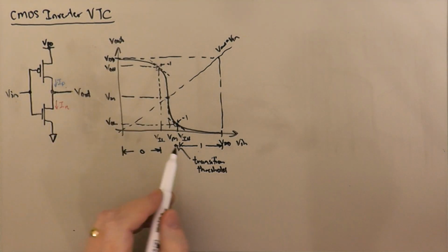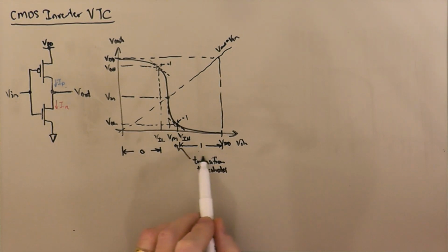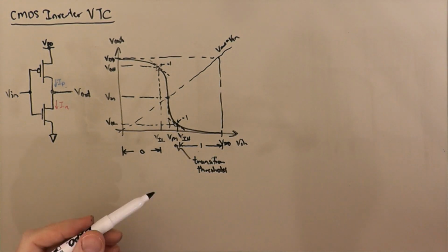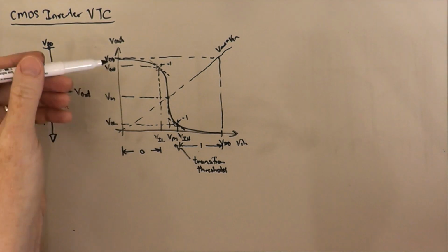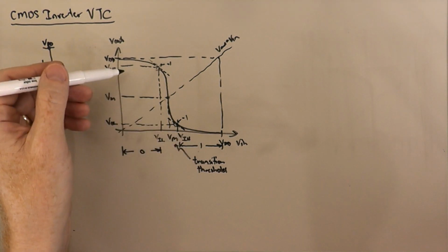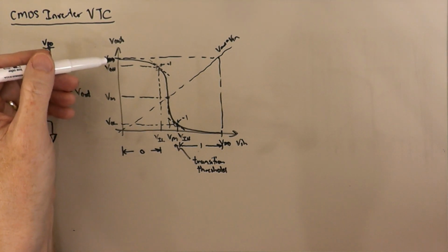Okay, so these ranges of input voltages that we consider valid logic low and valid logic high, if we operate in those ranges, we're going to have nice quiet outputs, and the gate will basically squash that noise for subsequent stages.